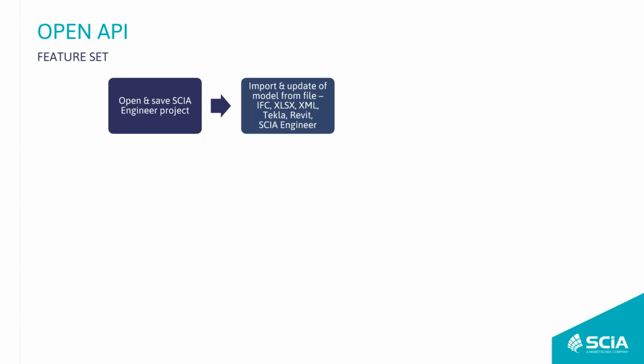If I have opened an empty project, I'm able to import or update a model from a file, where we are supporting IFC files, XML, and files which were created as an export from Revit or Tekla.